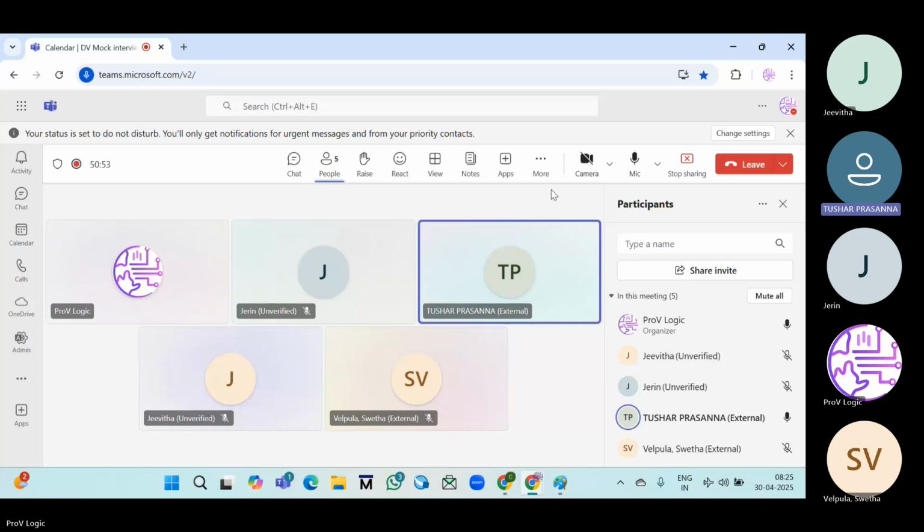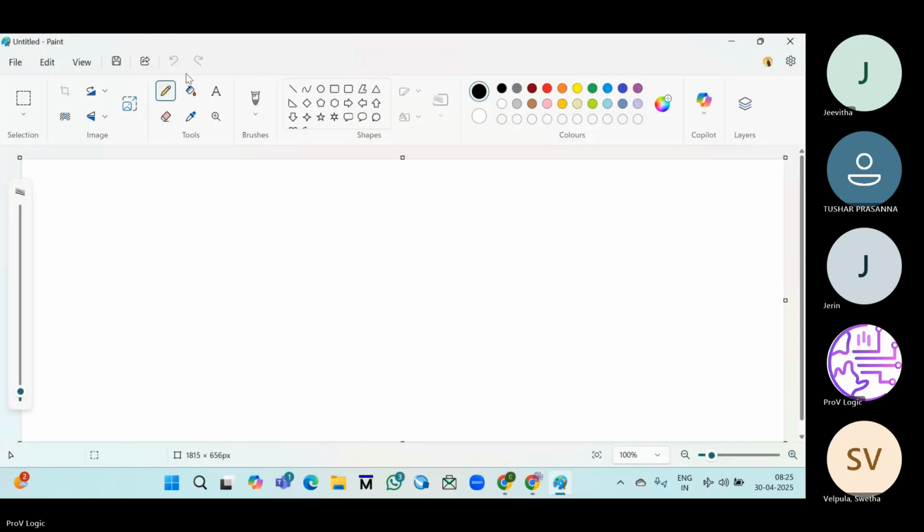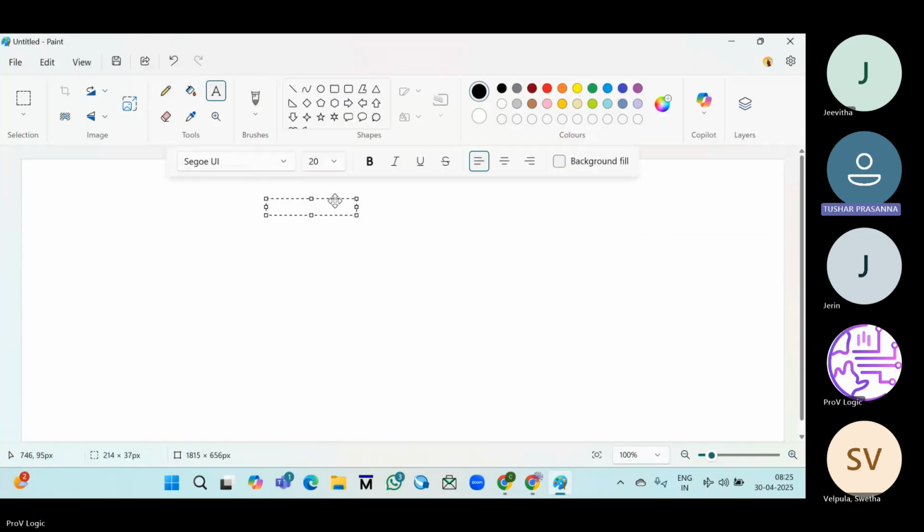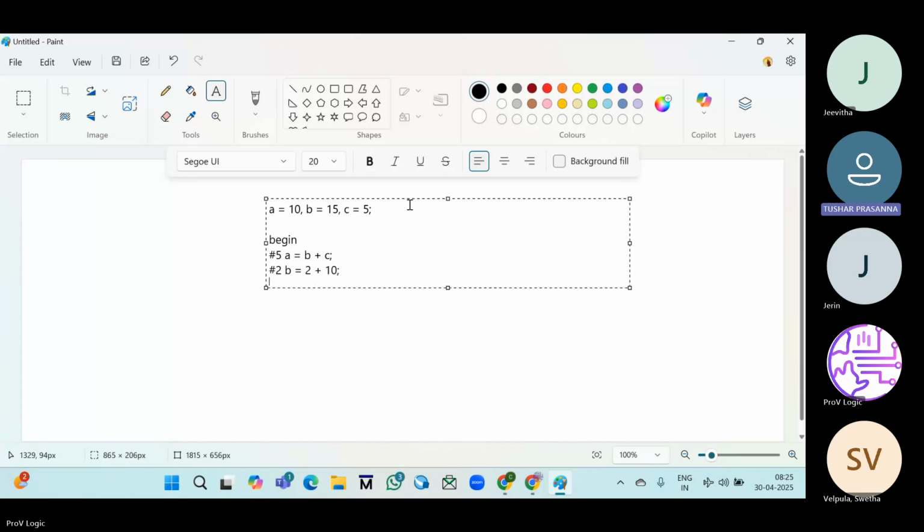For non-blocking, we use the less than equal to symbol, which does concurrent execution. For blocking, it happens line by line, where if the variable value changes on the first line, it affects the next line as well. But for non-blocking, it happens after the next clock cycle. And also for non-blocking, the delay is on the RHS instead of LHS, I believe.